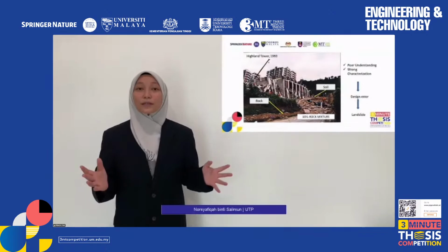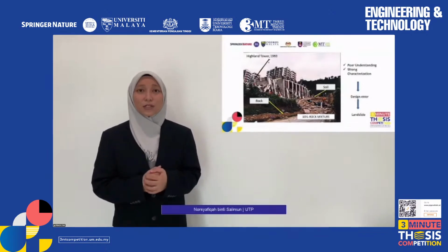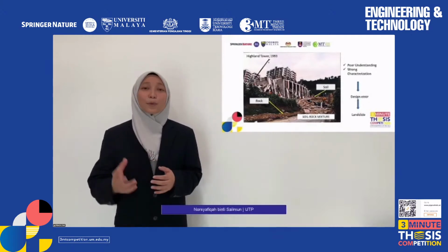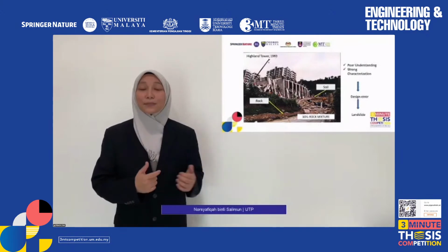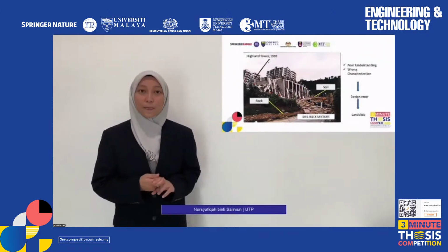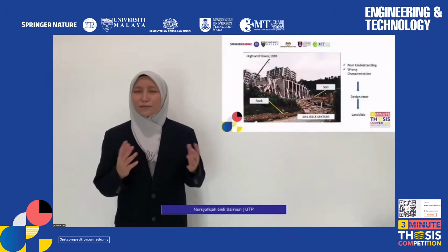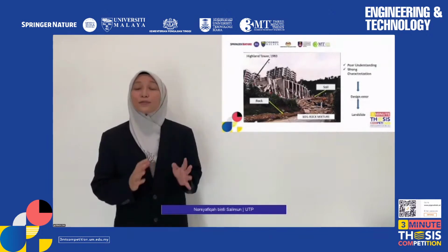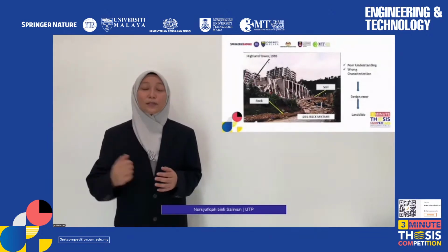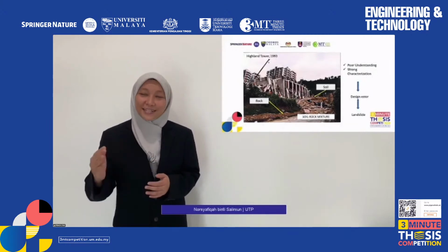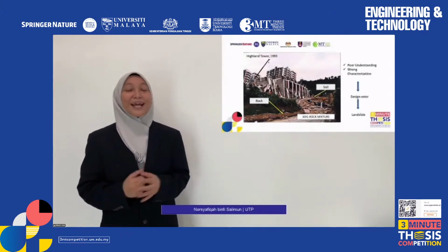And in nature, soil and rock can exist naturally as a mixture, or what we call soil-rock mixture, or SRM. SRM are loose material composed of fine-grained soil and certain percentage of rock blocks with various shape, size, and strength. Thus, SRM are extremely inhomogeneous and complex, but they are often treated as homogeneous to avoid tedious analysis, and this could lead to design error. So how can we properly characterize them? This is where my research comes in.